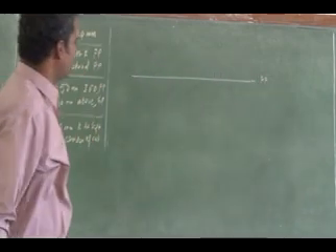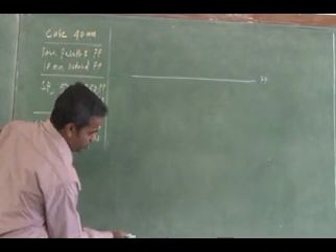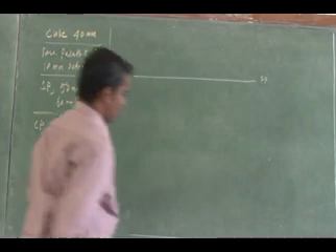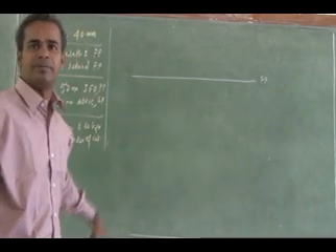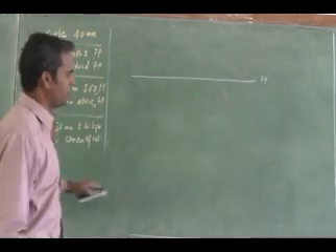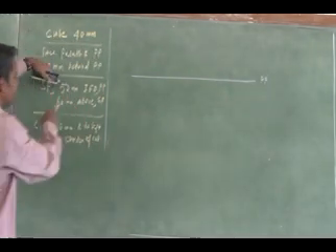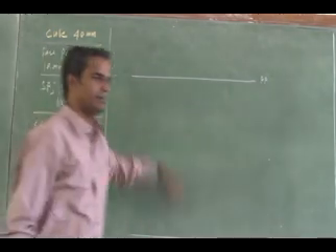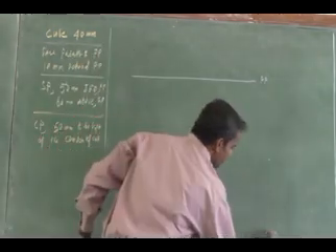So immediately you draw the ground plane on the bottom, right? Ground plane. Leaving sufficient gap between picture plane and ground plane, almost 150 mm you give approximately, right? So including this 50 and 60, 110 to 150 you give as the gap. So this is my ground plane.